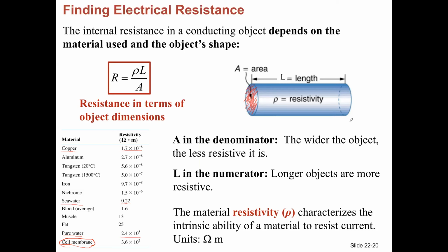The power plant causes this whole oscillating current through the wires. The reason is that any one charge doesn't have to move very far. It just oscillates back and forth, and that limits the amount of resistive losses we get. This is one of the reasons why we use alternating electrical current for power transfer rather than direct current. So that's a very good question. I hope, at least I think, that's what your question was.